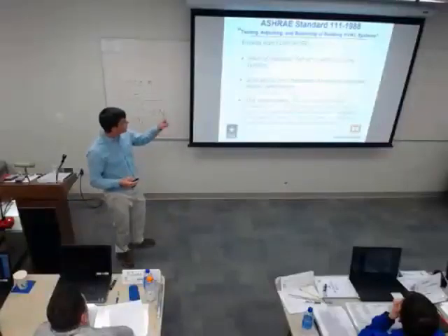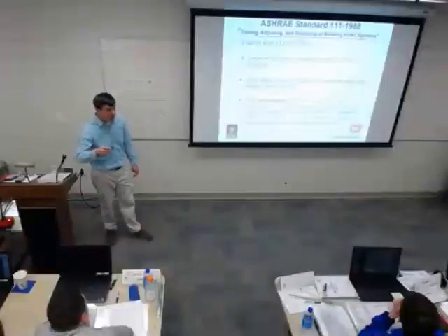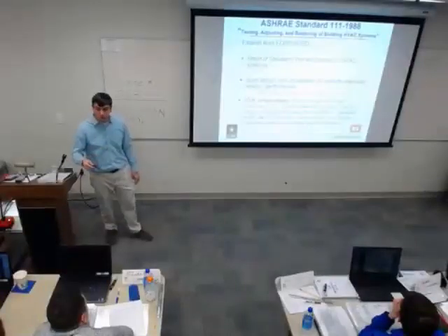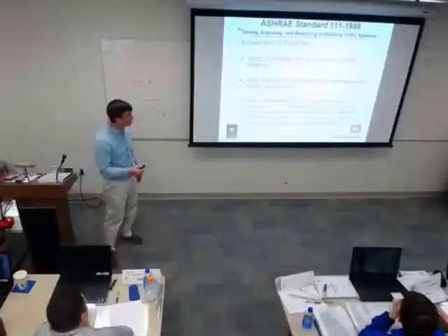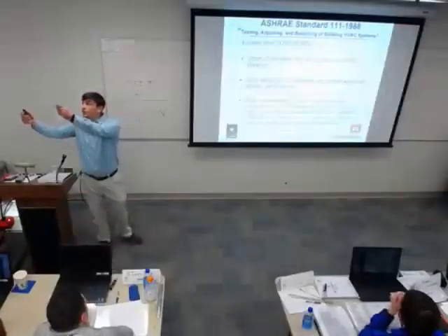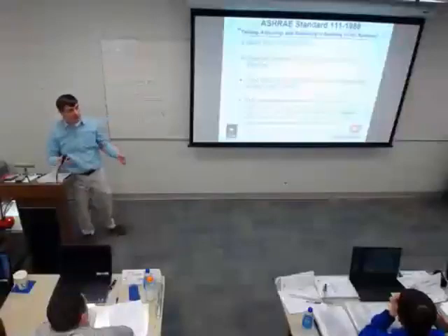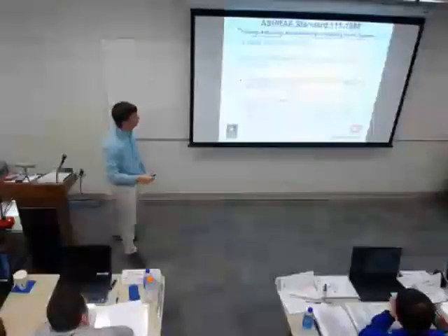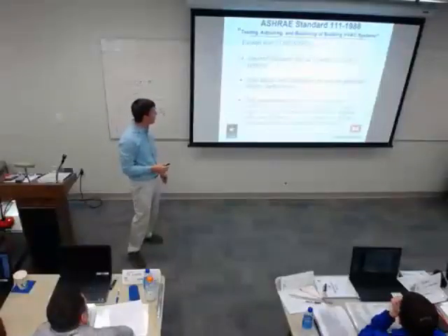All right, I meant to move this to the front because this kind of goes along with what we were talking about earlier. How close is close enough, right? Our spec says 5%. But that's only for the actual measurements. I measured this diffuser right here. I need to be within plus or minus 5%. There's some of this stuff that isn't dictated by the specs. One thing to keep in mind, not all is perfect.